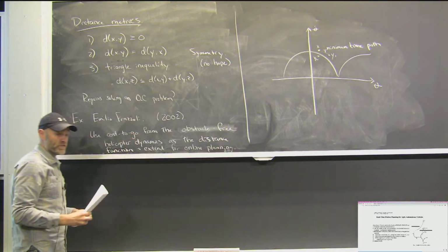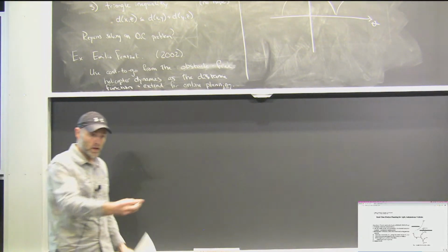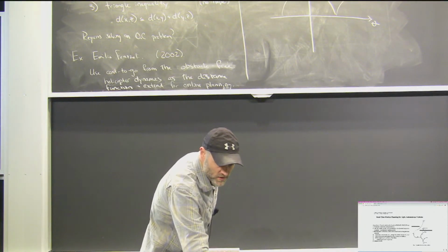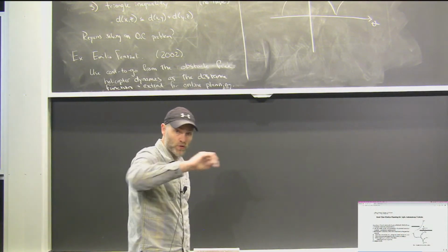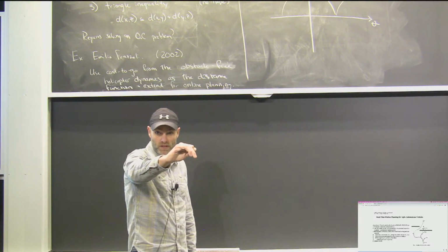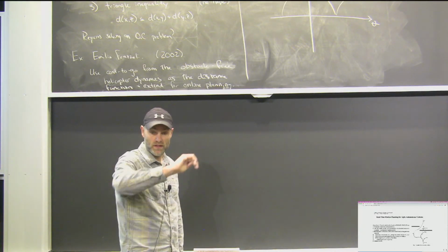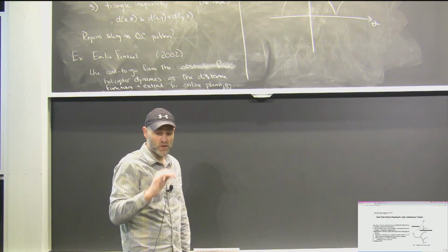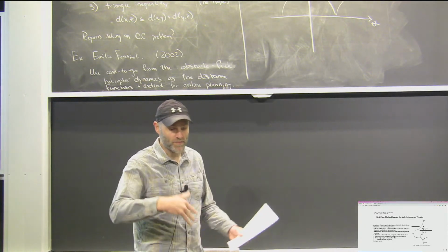And he was able to do real-time planning with that setup. So growing the tree with these, you notice also that the tree he illustrates here and the trees that he got out of his algorithm were characteristically very different than the trees I just drew that were super dense. These are relatively sparse trees that take long winding trajectories because you can trust your dynamics, your distance metric and your controller to take relatively longer extend operations. So you can have relatively much fewer samples in order to get around this and do everything on the fly, on board these days.